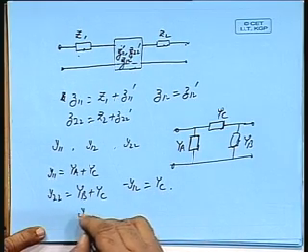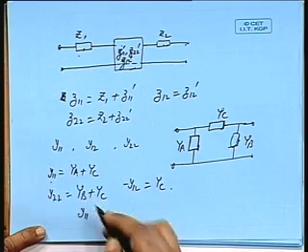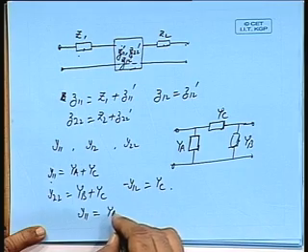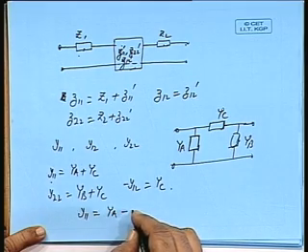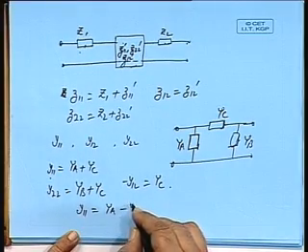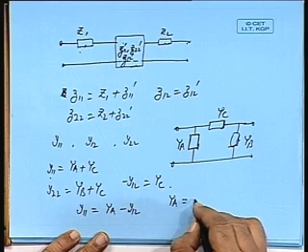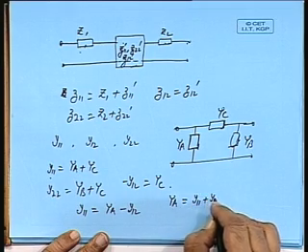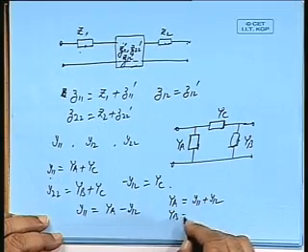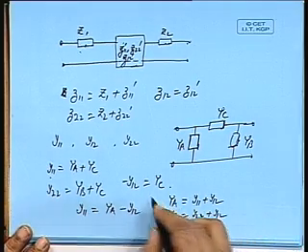So, y11 minus y12 is ya, is that all right? Or ya you can write as y11 plus y12. Okay. Similarly, yb will be y22 plus y12, and yc is minus y12.